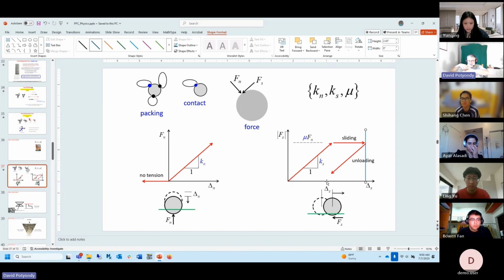Somehow I started with 0. I forced my finger to move, and now just think of the finger on the hand. It starts sliding, and now if I unload till it gets to 0, it's got a permanent motion. And so during the sliding, you are dissipating energy. Energy is naturally being consumed in that process. While you're sliding, you're not storing any more energy in the spring. So friction in a system is a source of dissipating energy. Did you guys follow that?